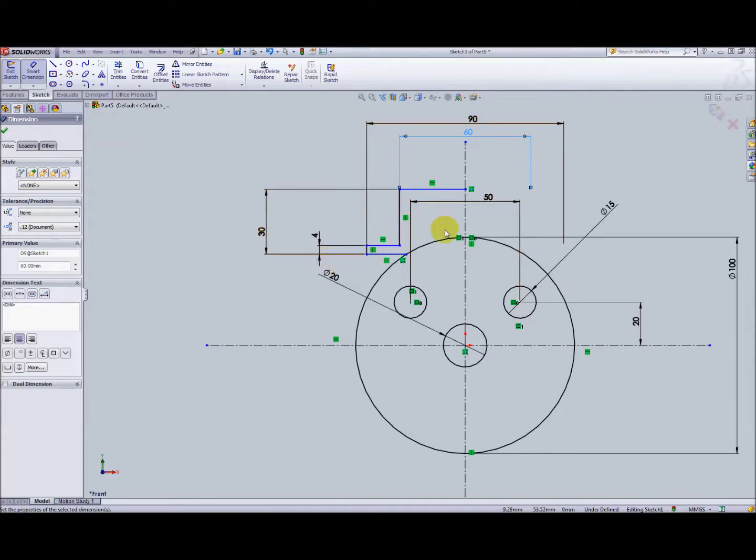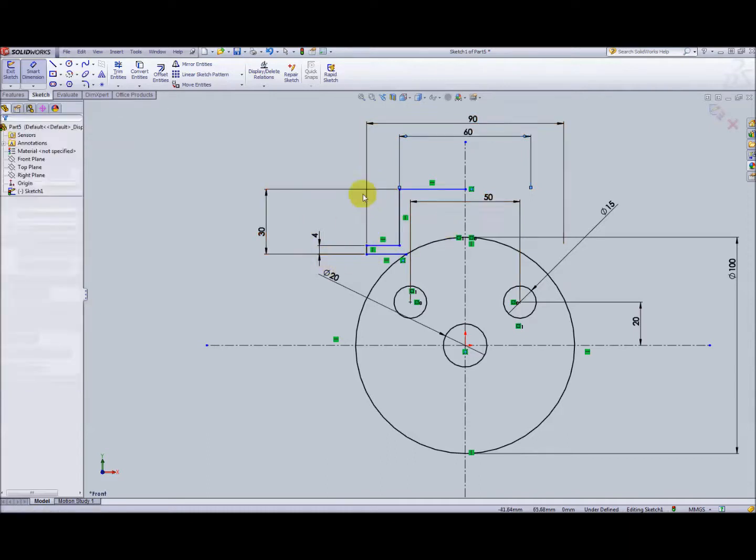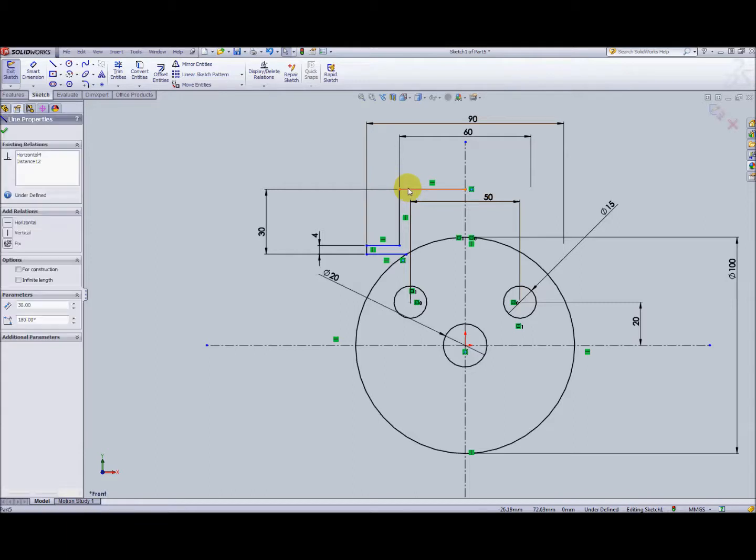One of the techniques, if we're not sure why this is blue, one of the techniques that's really useful is just to grab one of these blue bits of geometry and try dragging it. Now you can see that what happens here is that the bits that are constrained won't move, and the bits that are unconstrained will. And now we can see that the only thing we don't know is really what the position of the hat is in relation to the head. So basically how far down the hat is from the head.